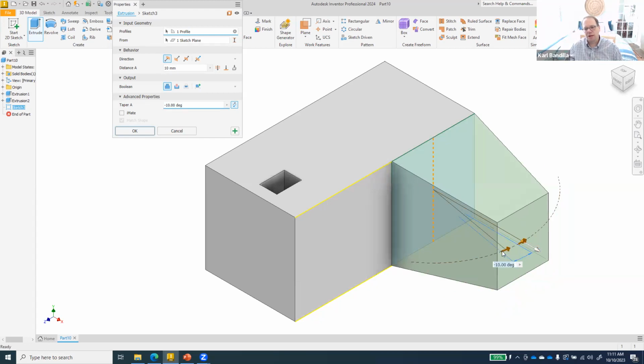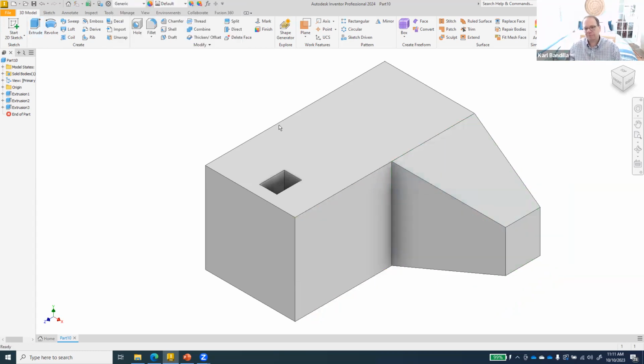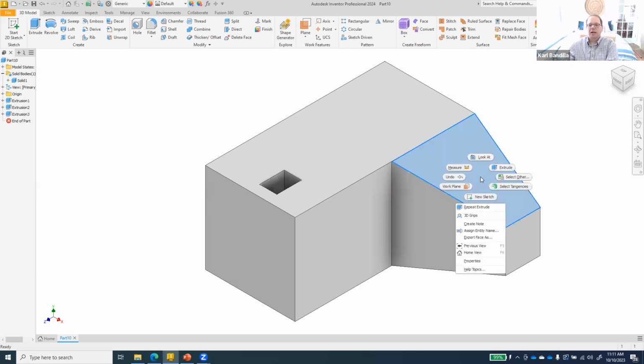I don't have to do it by hand, right? I can do it up here too if I wanted to have, whatever, minus 15 maybe, and there we go. We just created a new part. Again, if we look at our solid bodies, we still only have that one solid body because we created that on there. Now, if we wanted to create a new solid body, again just for completeness, I can draw on this surface as well, right? It's just a sloped surface, so that's fine. I can do that.